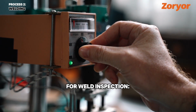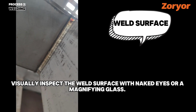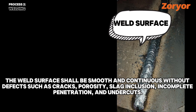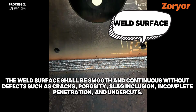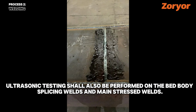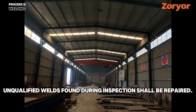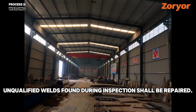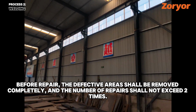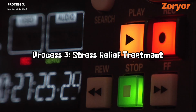For weld inspection, visually inspect the weld surface with naked eyes or a magnifying glass. The weld surface shall be smooth and continuous without defects such as cracks, porosity, slag inclusion, incomplete penetration, and undercuts. Ultrasonic testing shall also be performed on the bed body splicing welds and main stressed welds. Unqualified welds found during inspection shall be repaired. Before repair, the defective areas shall be removed completely, and the number of repairs shall not exceed 2 times.